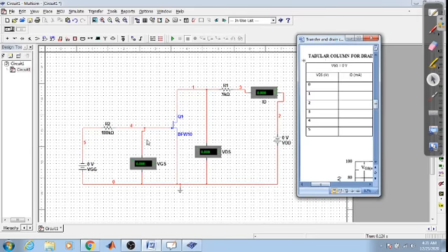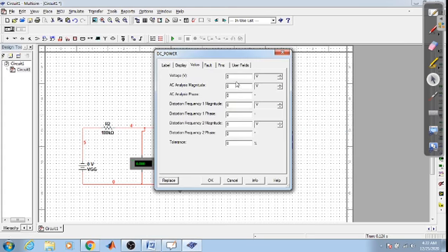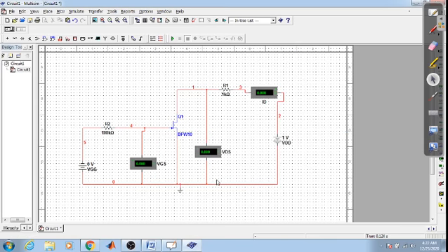So we have done VGS as 0. Now let us make VDS with some values of current. First let us make this as 0 volt. For 0 volt, obviously the current is 0 itself. Next for 1, let us make this as 1 volt.